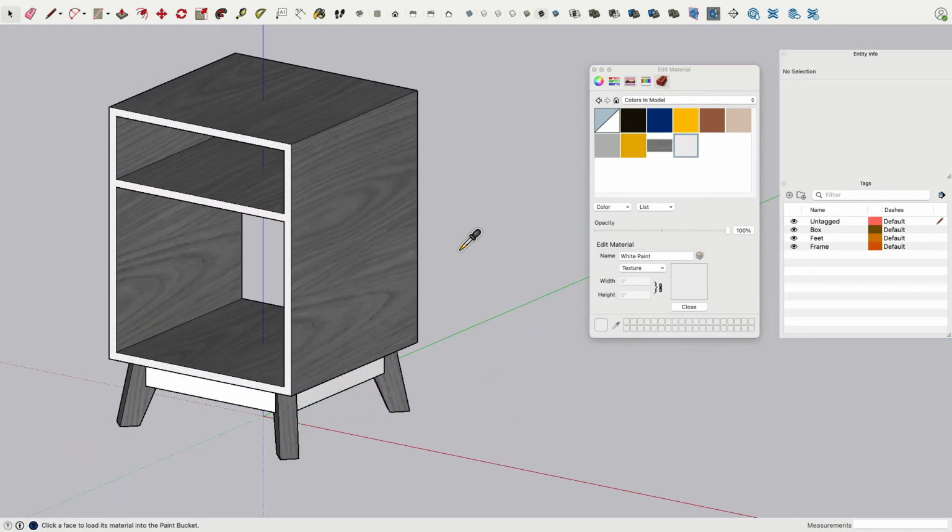Yeah, and honestly, that is pretty much everything in a nutshell about how to create a texture-based material in SketchUp, Mac, or PC, and then how we can set the scale of the image and apply this to individual faces, never the group and never the component, and then even rotate, etc.